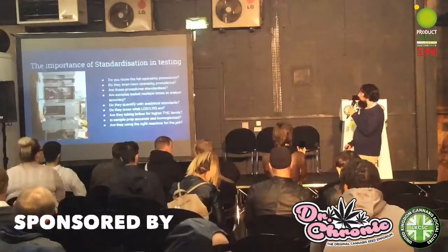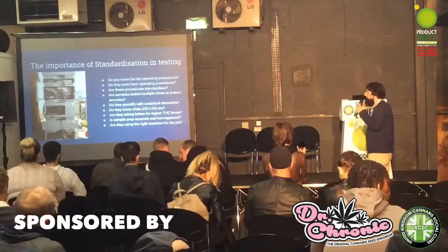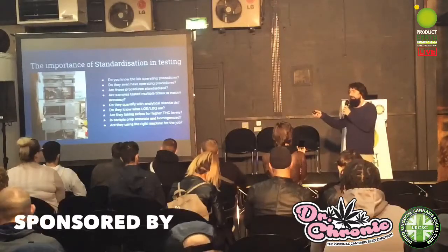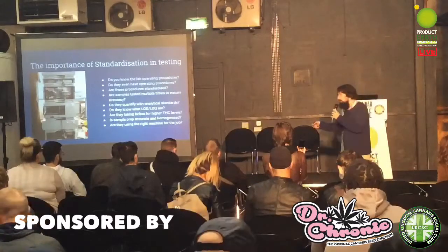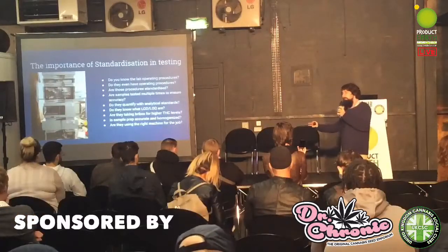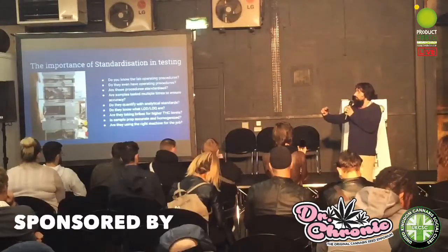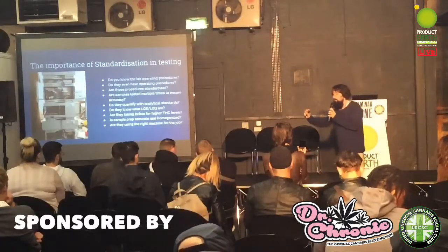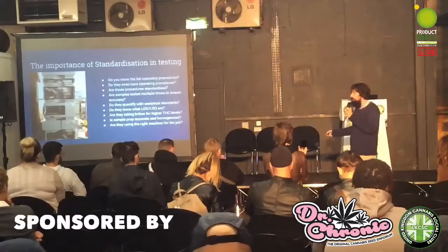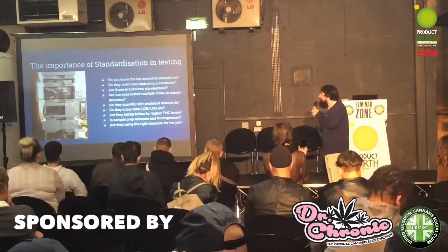Do they know what LOD and LOQ are? That's the limit of detection and limit of quantification. These machines are incredibly sensitive, but they're not perfect. You can't tell if there is anything below a certain point in there. The machines have background noise, and distinguishing a compound present at such tiny levels from background noise on the machine, you often can't do it. Those are your limits of detection and quantification.